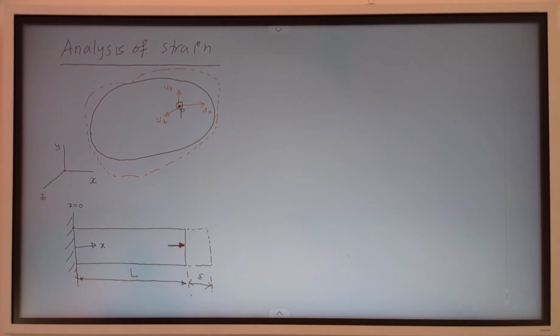So there are two modes of failure. One is the mode where the equipment will break. There will be some crack, it will get joined or welded, there will be some plastic deformation. So that is the area we have studied till now, that is the stress analysis, where you calculate stress or the internal resistance of the body and compare it with the material permissible limit, that may be yield strength or ultimate strength. That is one approach.